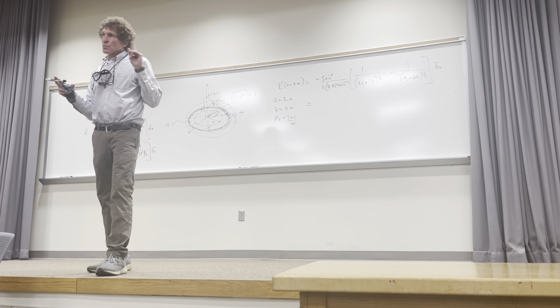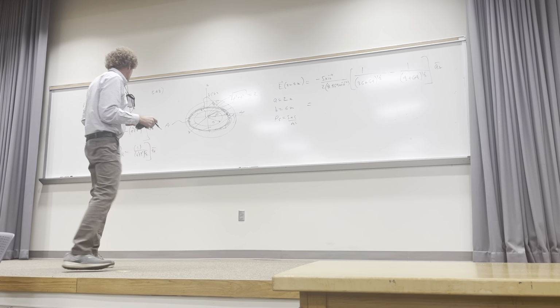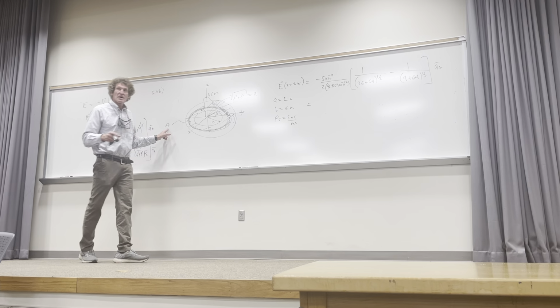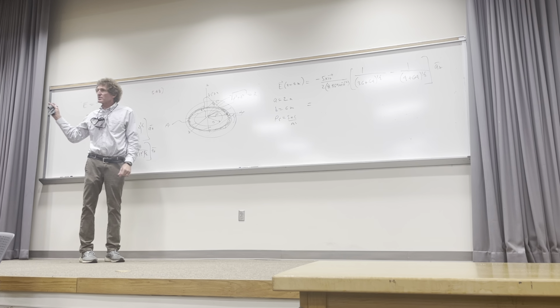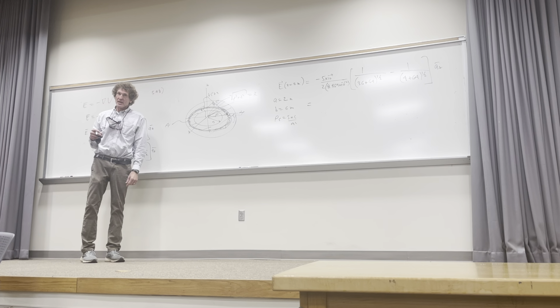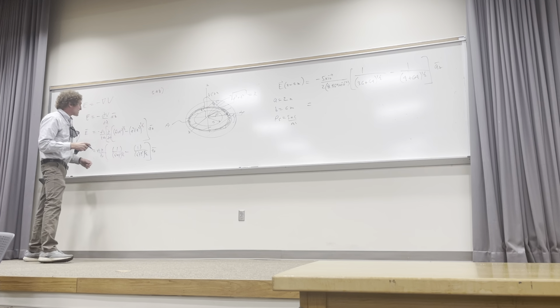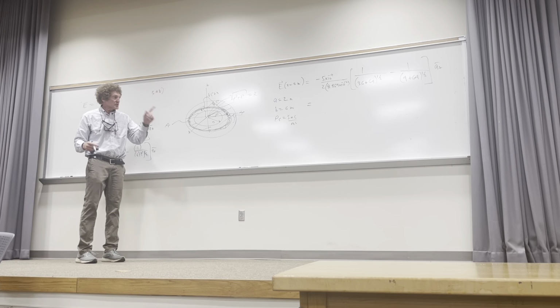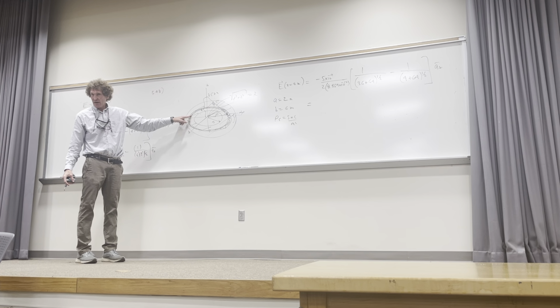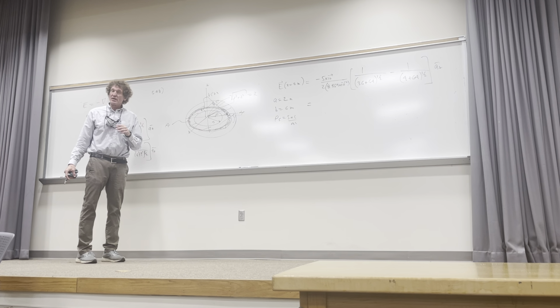And the problem is with one change, if I change rho s to make it a function of position, all of a sudden all those formulas aren't worth a hill of beans. Then you have to go and get the differential voltage from a given sliver there, right? And rho s is a function of position rho. Then you would have to do the integration to get the total value of the voltage.